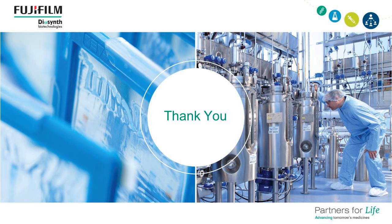So specifications are actually the first thing that we teach when we teach process validation training here at Fujifilm. We actually believe that process performance qualification really doesn't start with the process itself, but actually starts with the specification and works backwards. So you'll see the tools that we talk about, whether it be the process attribute map or all of the other characterization itself, actually starts with the specifications in mind. Understanding where that specification comes from is quite pivotal. We like to bunch specifications into one of three categories: safety, efficacy, or manufacturing reliability. And for each one of those, the sources of those specifications and the implications on manufacturing need to be considered from day one.